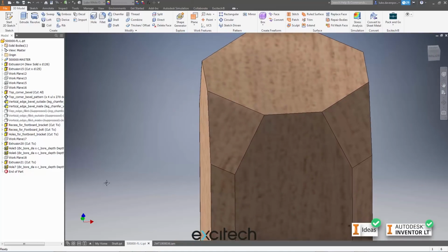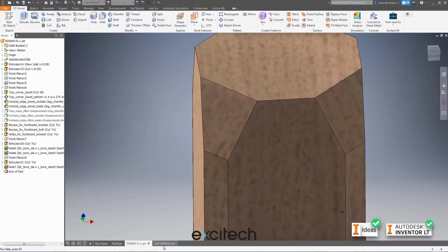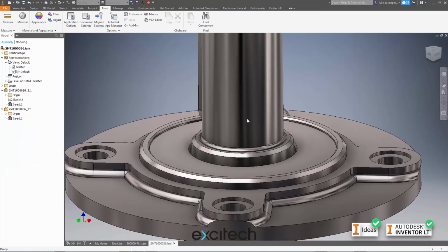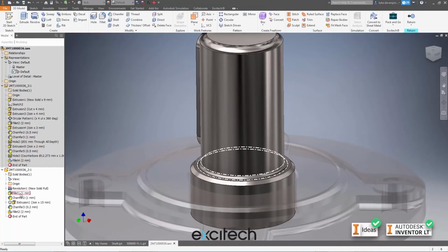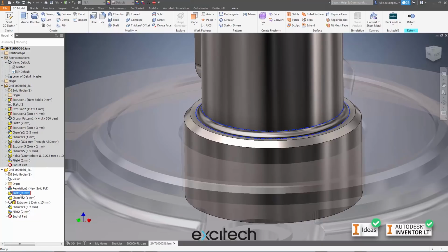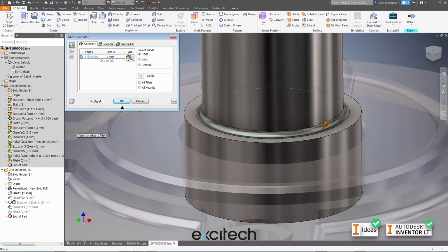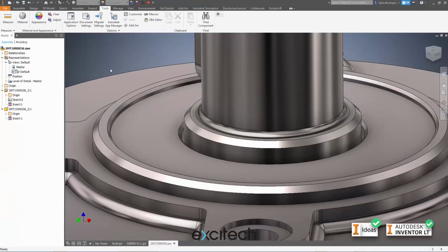Okay, very last thing for this fillet tool, if you're working in an existing part that's got a fillet, and you try and edit the fillet here, I think even with a migrated part you won't get the option to do the inverted fillet, so you'd have to delete the existing fillet on a 2018 part and recreate it with the new fillet tool in order to be able to invert it if that scenario does actually come up.